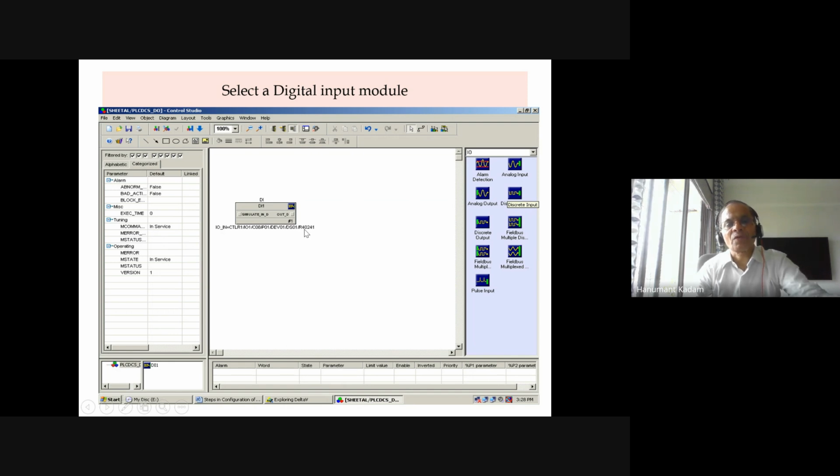And this is a register value, which means a PLC interface: the PLC has been connected through the serial interface card to this DCS controller. So this is the entire tag showing where this digital input is coming from, now to this card. This is the card.